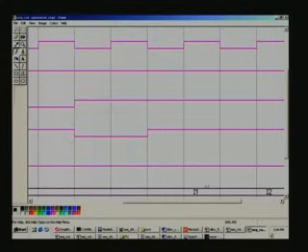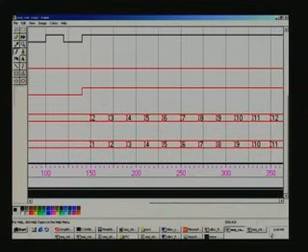That means after all, the synthesis is aware of the gate delays, because it has mapped onto the actual primitive cells that Xilinx's place and route is ultimately going to use. So whatever place and route details supplied by Xilinx have been incorporated. It may not be in depth, maybe interconnection delays are not fully accounted for, and that is the reason why we need to go for Xilinx place and route. So you have some sort of delay element also coming into the picture, that is why you are able to see this. Let us compare this with the previous one.